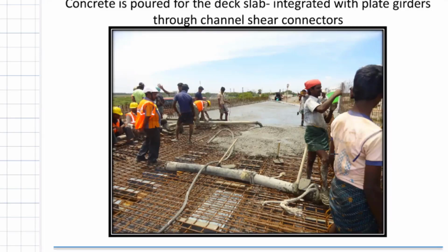I give a nice walkthrough of how a steel concrete composite bridge is built. I have a span to be there. I'll get a line block from the railways, lift girders one by one within the time window. Once they're done, the traffic is resumed. Then in the lean period, I put all the cross girders. Once the cross girders are on top, I'll put all the shutters, sometimes wooden planks or sometimes steel deck sheets. After that, I put the concrete and, of course, you're ready for the traffic.